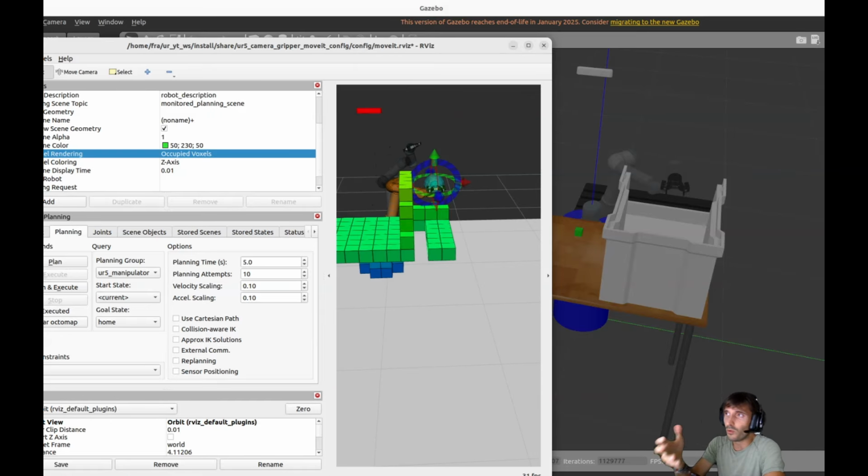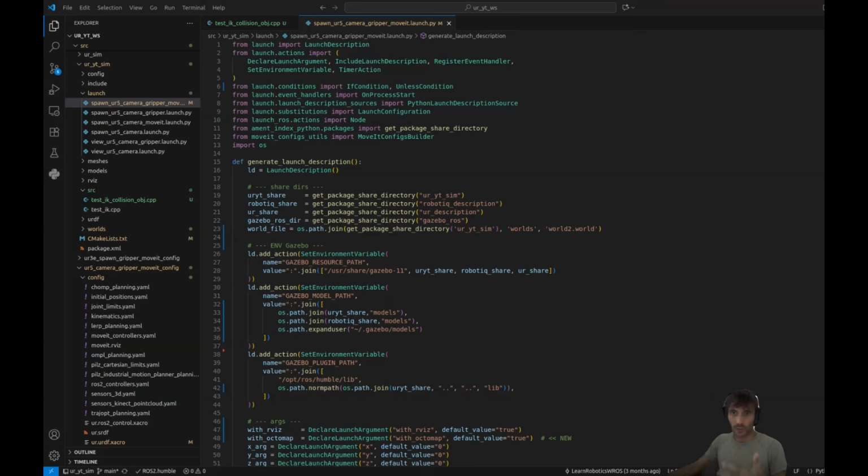Okay, even though this is not the right manner to run this motion planning, because we weren't able to reach the target position by picking the object, I wanted to show you this very useful tool from MoveIt, because you can run obstacle avoidance very easily by letting the camera do its job, or better, transmit this data to MoveIt.